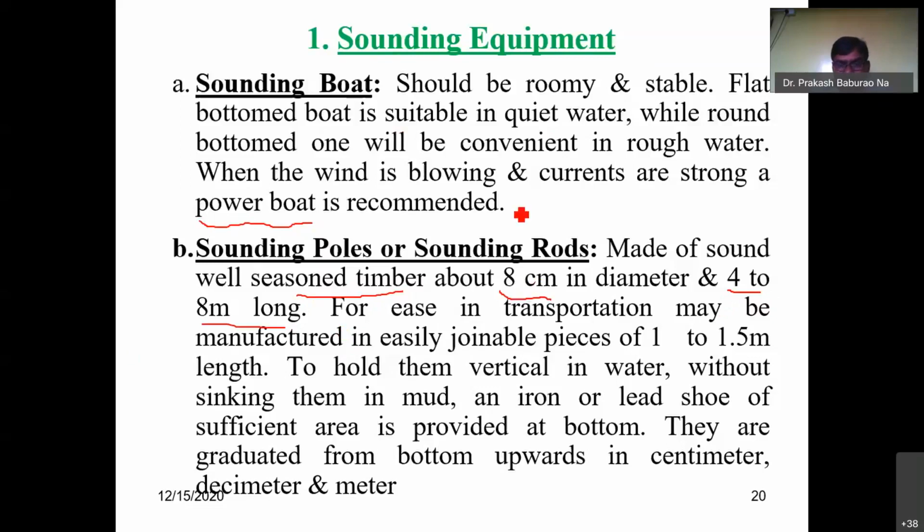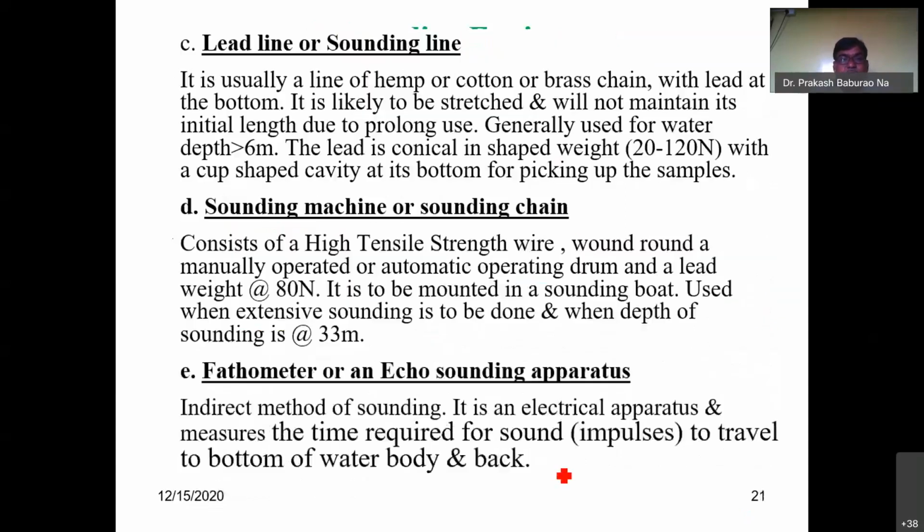And it has been graduated, and you have to go with the actual measurements of the water, because these graduations have to be marked on these sounding poles, or in some cases you have to utilize the sounding rod. So you are getting the information about the depth of the water.